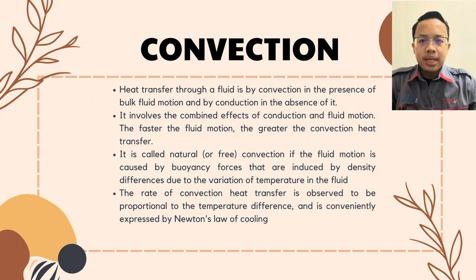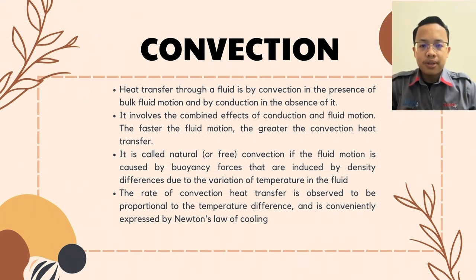In this experiment, it is called natural convection because the fluid motion is caused by the buoyancy force that is induced by density difference due to the variation of temperature in the fluid. The rate of convection heat transfer is observed to be proportional to the temperature difference, and it is conveniently expressed by Newton's law of cooling.